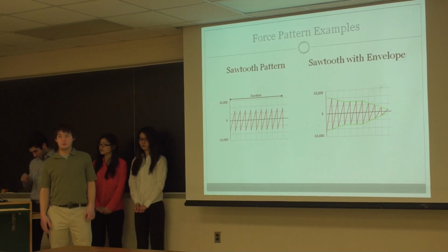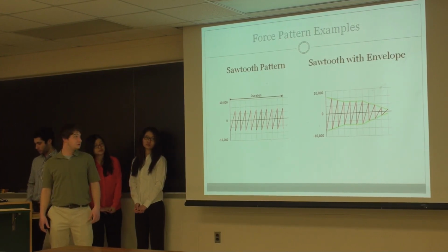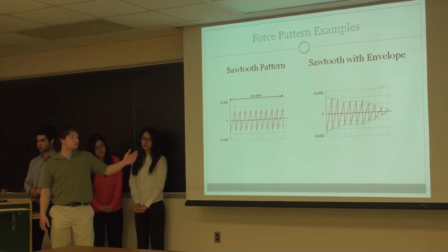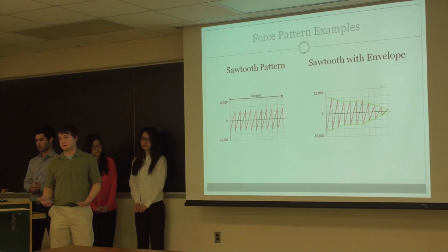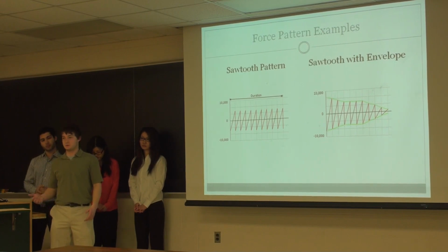And here are a couple examples of force feedback patterns. Both of them are actually periodic forces. Say for instance you assign a sawtooth pattern force in the x-axis of a joystick, and we call it negative force to the left and a positive force to the right.